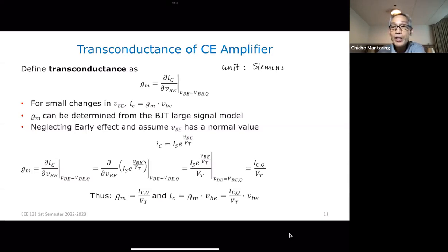Okay. Now, why do you call it a transconductance? It is called a transconductance because the voltage is not in the same circuit as the current. The voltage is not across the same element; the voltage is in another part of the circuit, basically.